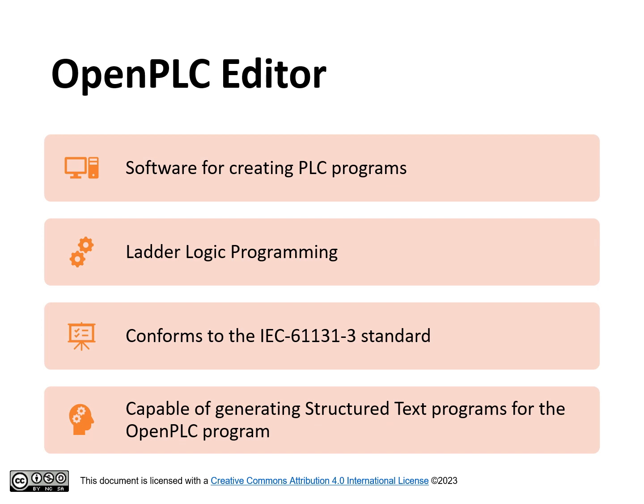The OpenPLC Editor is software for creating PLC programs according to IEC 61131-3 and conforming to PLCopen XML. It was created mainly by Edouard Tisserant and Laurent Bessard for the Beremiz project. The OpenPLC is capable of running structured text programs. OpenPLC Editor can generate ST programs for the OpenPLC out of all of the 5 IEC 61131-3 standard languages.